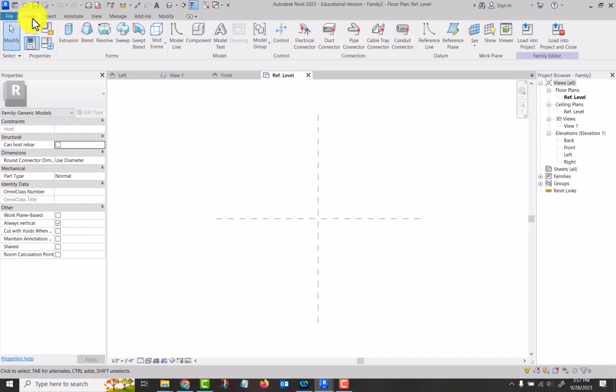Now, before I even start with this, it's critical that you do your extrusions or your creations on the correct surface plane. Now, think through what it is you're going to create, and your sketches have to be done on the right plane. Like I've said in the last video, if you've taken the Inventor class, that will be a little bit more intuitive to you.